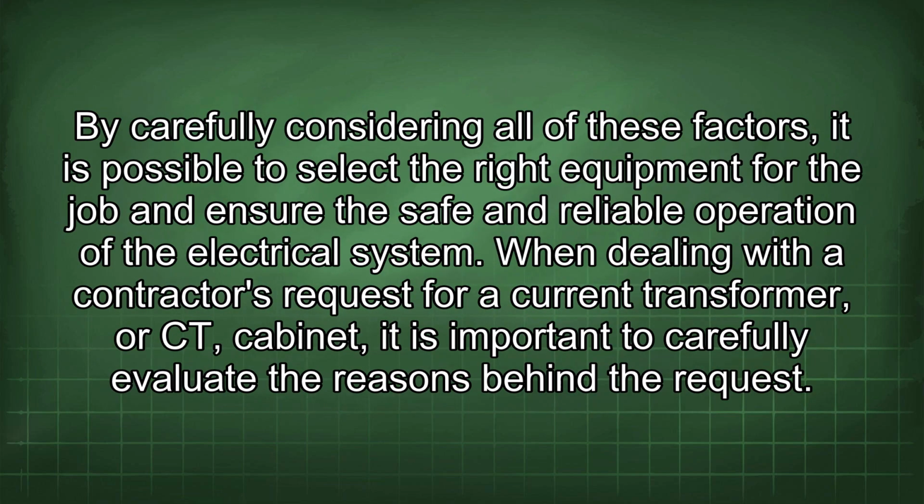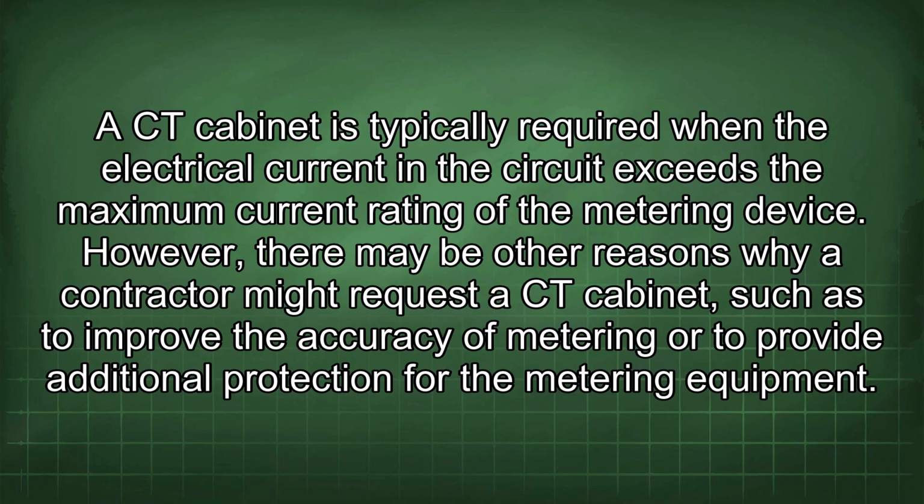By carefully considering all of these factors, it is possible to select the right equipment for the job and ensure the safe and reliable operation of the electrical system. When dealing with a contractor's request for a current transformer or CT cabinet, it is important to carefully evaluate the reasons behind the request. A CT cabinet is typically required when the electrical current in the circuit exceeds the maximum current rating of the metering device.